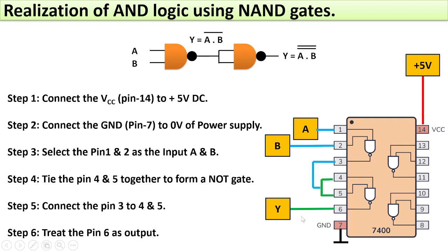We have to remember one thing, that the output can be measured using again a digital multimeter. So you will have to connect the input wires following all four combinations: first connect both to ground, it will be 0 0; connect any one to +5, it will be 0 1; then vice versa; and for the last one, connect both of them to +5. This will actually create a circuit which realizes the AND function.